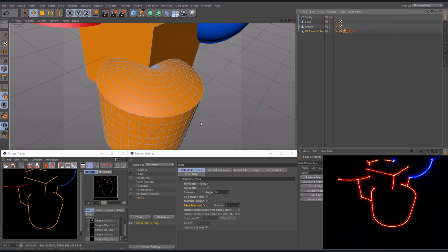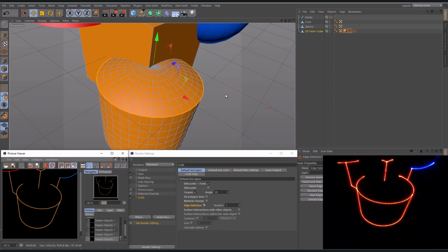We now have 2 selections, and by using the number 1 or number 2 selection from below menu, you are able to show those lines in sharp quality inside your rendered frame. This here, for example, is this outer line we selected as number 1. The very good advantage of this edge selection tool is that you are able to show only dedicated lines based on your previous selection.